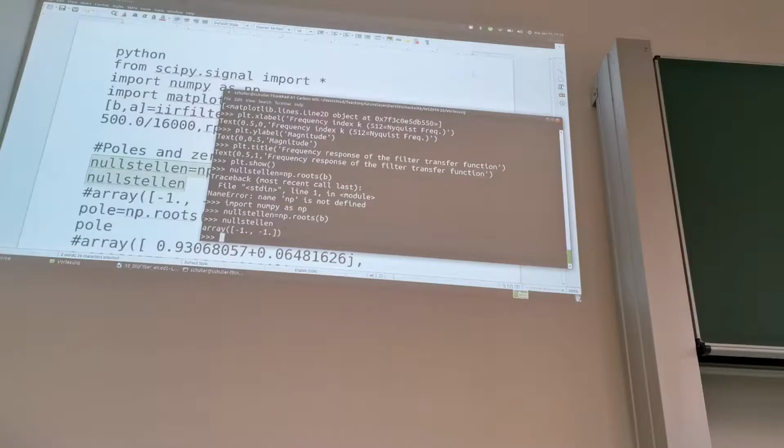Yeah, which means which normalized frequency? Remember, we have this e to the j omega, that's normalized frequency in the complex plane, this pointer. So omega is 180 degrees or pi, right? And pi is what frequency? Nyquist, right? So this angle in the complex plane is identical to our normalized frequency.